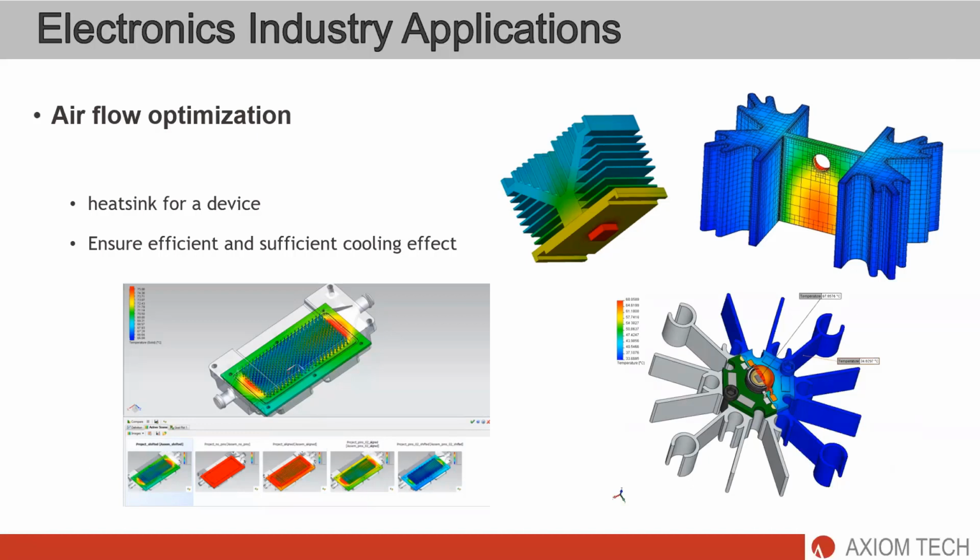The primary goal of this analysis is to select the most suitable heat sinks for a specific application to minimize cost, weight, and pressure drop, whilst meeting temperature performance criteria and minimizing wake effect that causes disturbance of the downstream airflow.